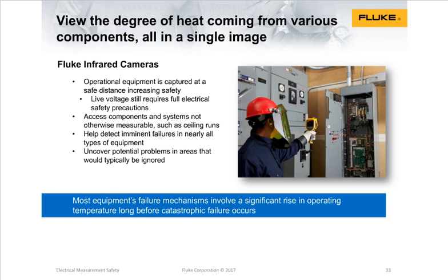Thermal. We talked a little bit about thermography. I'm excited to hear that 75%, according to the survey, are using thermography. I think we can improve on the number of people who are in fact putting in IR ports, which is an infrared port. It's an infrared window. I think I may have a picture of one coming up.